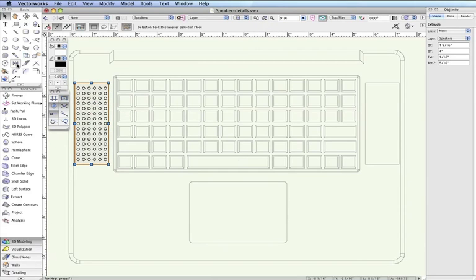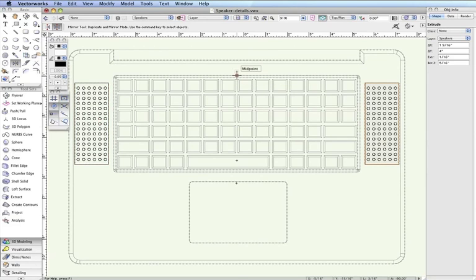Be sure the second mode, Mirror and Duplicate, is enabled in the toolbar. Now, move your cursor toward the center of the top edge of the CPU case. Click once the cursor cue midpoint is displayed. Hold the Shift key and move your cursor downward, then click again where the cursor cue vertical is shown, to place the duplicate speaker on the right side of the CPU case.